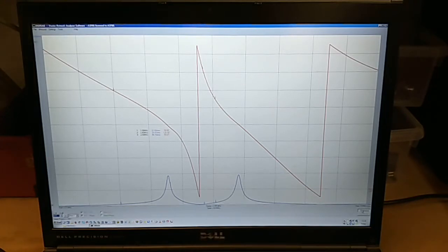So as the energy is used up in the primary, with the high Q system, which this is, the oscillations continue in the secondary, and you see those two distinct frequencies. You see the resonant frequency of the primary, and you see the resonant frequency of the secondary.